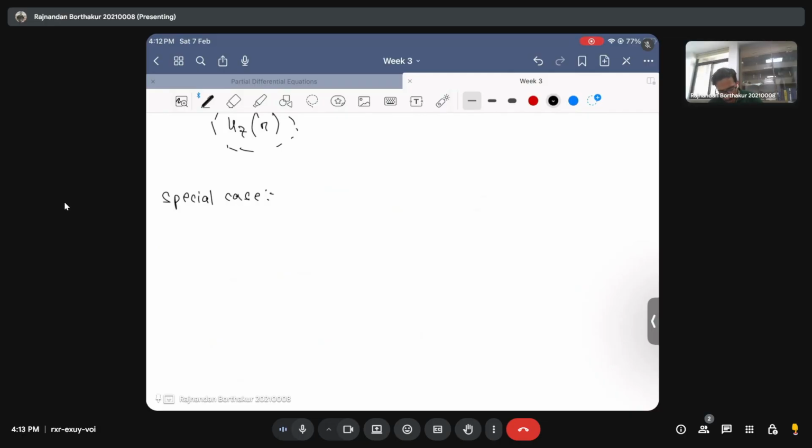So that's a special case where I'll say that my dpdz is equal to 0, which means that now there is no applied pressure gradient in the axial direction, and this will mean that there is no actuating force in the z direction, which will then imply that my uz is also going to be equal to 0, just like u theta. And then I also say that my inner cylinder is absent, which means that I can consider a to be equal to 0, and I say that my omega 1 is 0, because if there is no inner cylinder, you can't have a rotation omega 1.